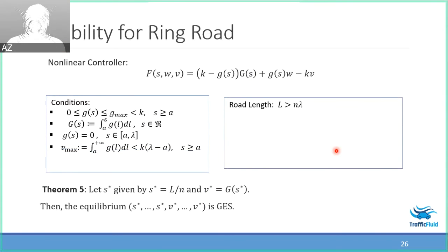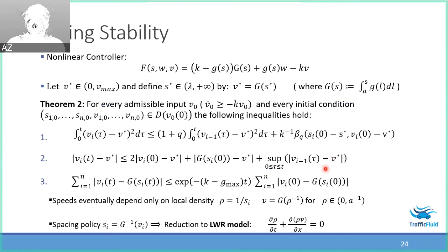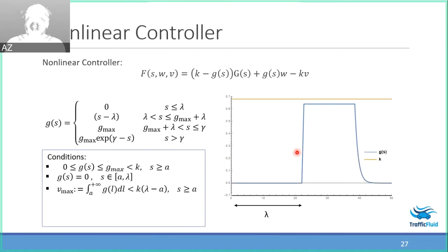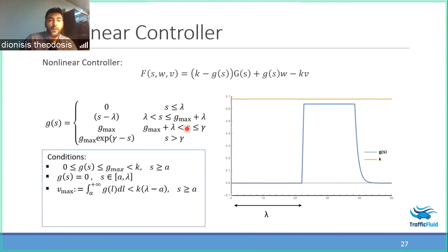Yeah, it's fixed. I just chose some. Let me go to the design here. I just chose these constants to satisfy the speed limit. This k also gives us the deceleration rate of the vehicle, the maximum acceleration. So first I designed it to have low accelerations to also satisfy this condition, and that was it. After that, the function g is trivial, given by this equation.